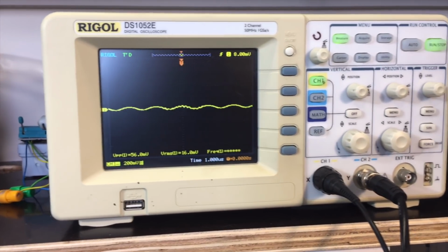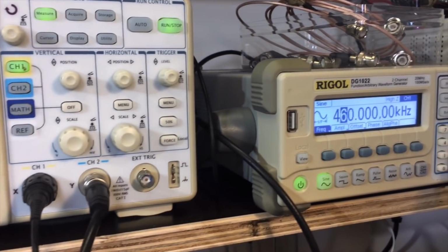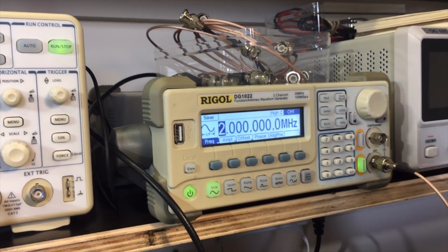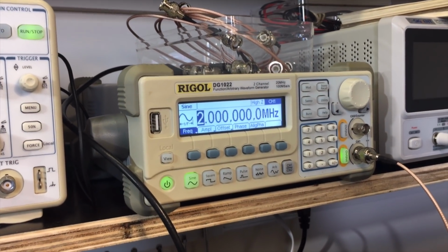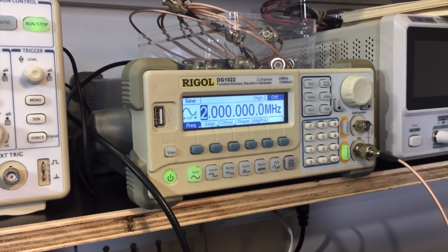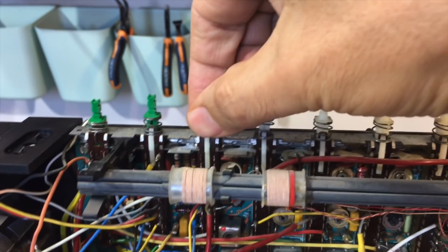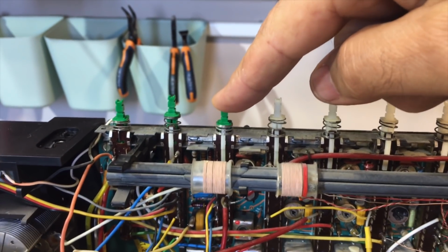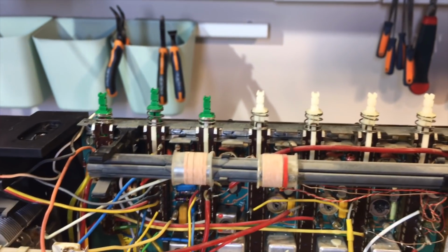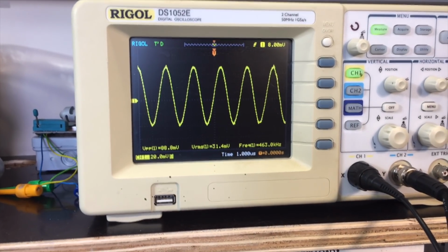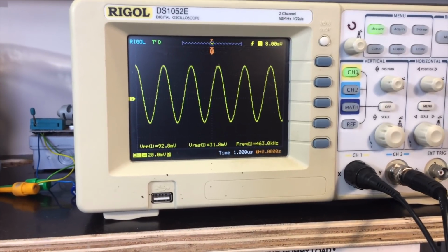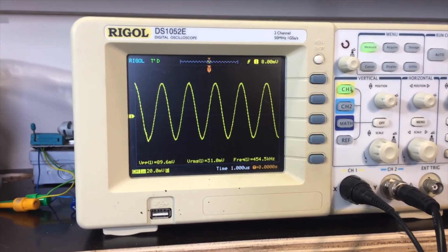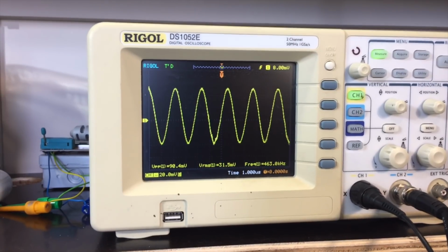So I'm effectively getting nothing there, but if I turn this to 2 megahertz, so now I'm sending 2 megahertz across, and I have to select K3, or rather shortwave 3 to 10. That's what we get. We've got our 460 kilohertz carrier wave there again at the same spot, which is sniffing it at the collector of T19. So let's see what we need to tune on there.